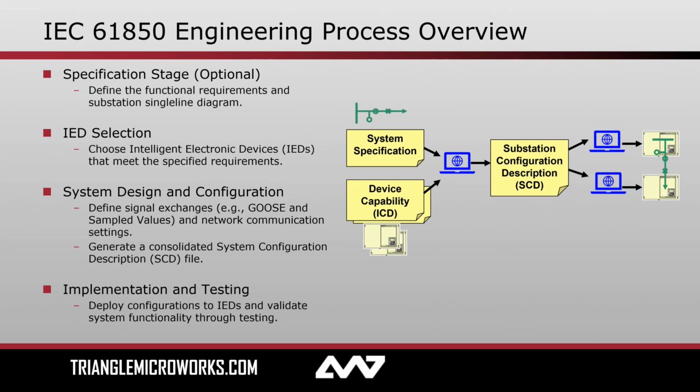There are vendor neutral tools like HELinks that we'll be talking about that can work with any vendor's IEDs, or if you're just choosing IEDs from a single vendor, a lot of different vendors have their own that only work with their own IEDs. But you'll spend a lot of time in this tool because it's where you're going to be configuring all of the signal exchange, all these GOOSE messages that we've talked about, configuring the data sets for those, same thing for your reports, the data sets where you pick out which data you actually want to transfer up to your HMI.